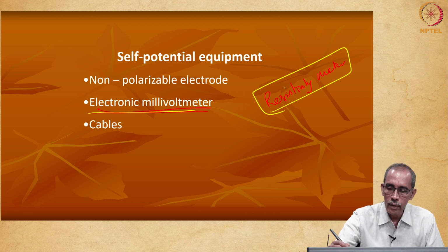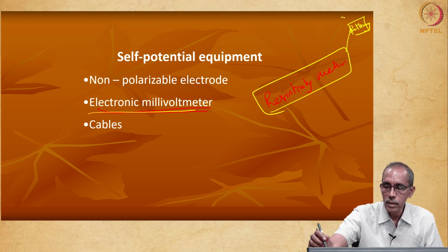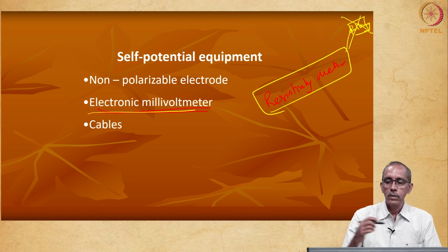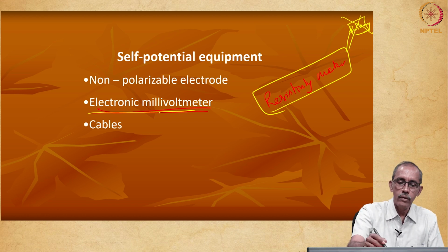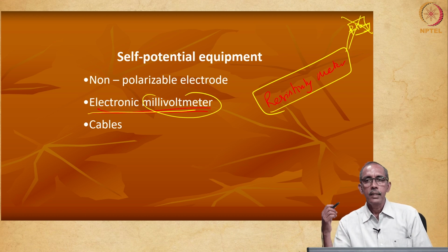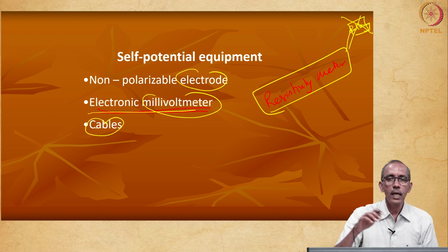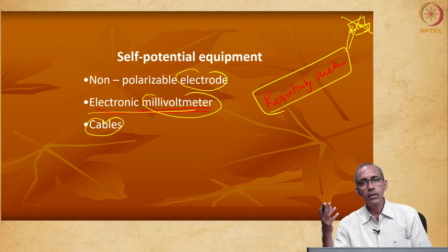So, resistivity meter we have already seen. Resistivity meter is attached to a battery, right? For conducting resistivity survey, we need to make use of the battery, whereas in cell potential method, battery is not necessary. So, it is sufficient we use the resistivity meter, or if we do not have resistivity meter, we can also use the simple voltmeter, right. Then we need electrodes as well as cables. Cables are just similar to the cables we had used for resistivity method.